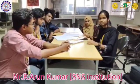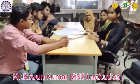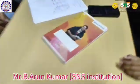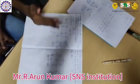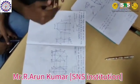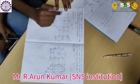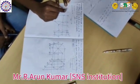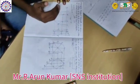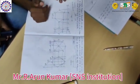Hexagon plate in the HP. So the front view for us will be a hexagon and the top view will be a straight line. So now the next will continue. Okay, I'm going to explain how to convert the 3D external lamina to a 2D diagram. So, I draw a reference line, and above the reference line is VP, nothing but the vertical plane, and below the reference line is HP, nothing but the horizontal plane.